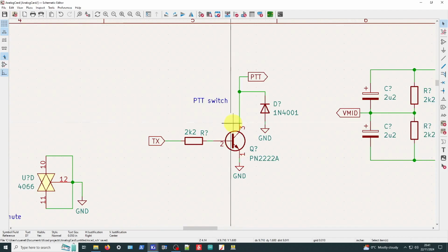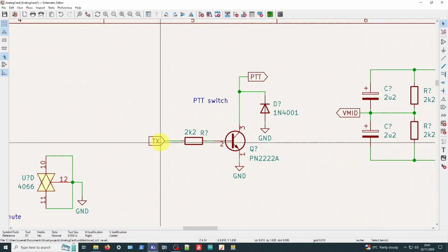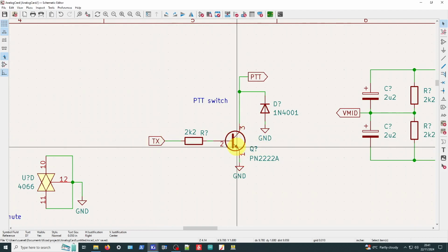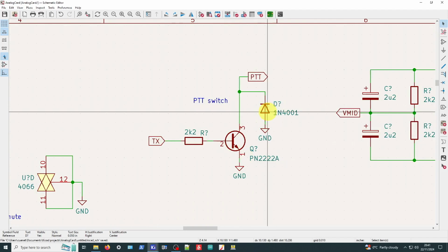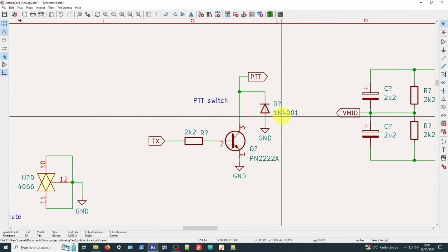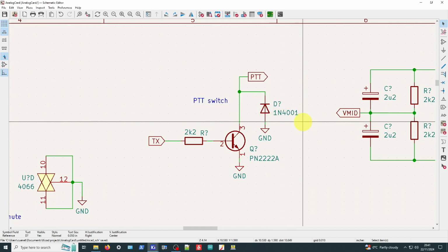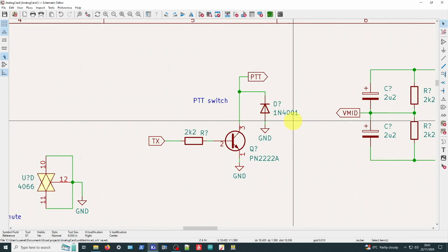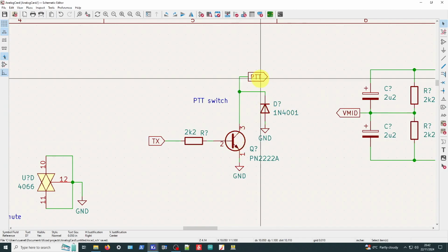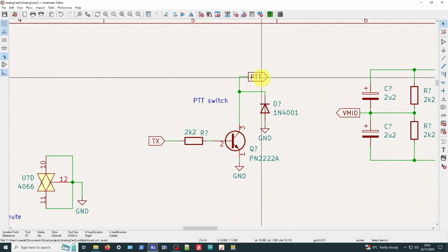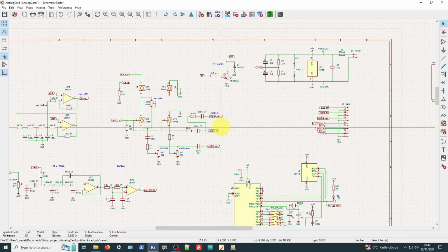This is the PTT switching circuit, so there's our logic level coming in here from the 6502 card. Very simple, a little switching transistor, and a little diode there for protection, to make sure nothing goes in the opposite direction and stops back EMF from coils or anything like that. So that protects the transistor up to a point. That's the PTT line which goes to the connector, which goes to the transmitter PTT line. And I think that's kind of it.